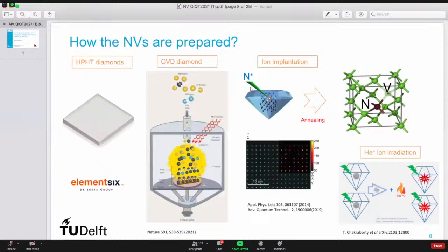The heating element creates a very high temperature and melts some metal inside. So the heating is around 1500 degrees centigrade. Then there is the source carbon atom from which we are going to basically create the diamond. That source carbon atom dissolves using that molten metal, and then it reaches a seed diamond which is kept at the bottom of the chamber. Then around the seed, the diamond is grown.